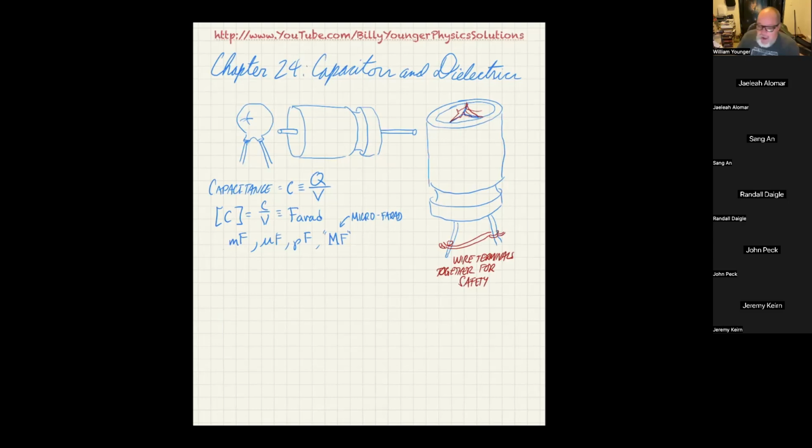If you need a grounded wire, by the way, remember your light receptacle in your house looks like this. I never remember which side the big eye is on, but this goes to ground. So you can take your wire, and don't mistakenly put it in the other one. Good Lord, it'll hurt. But you put it in that little half mouth down there at the bottom. As long as it's actually touching metal inside, then it's touching ground. You can then take the other end of the wire and touch things, and it'll discharge them for you.